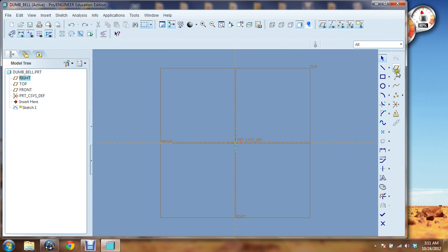Alright, so on your right now you see all the tools you can use in a sketch. We have line, we have square, we have circle, we have all this stuff going on. First thing I want to go over is just a line. Let's just go ahead and click that. We're going to come over here and we're going to go and drag it down. And we already noticed it's trying to lock it into a vertical position. Pro Engineer will go ahead and do that for you.